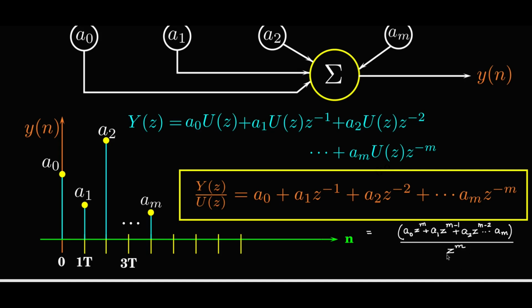However, all the poles have to be at z equal to 0. So therefore, in an FIR filter, there is flexibility only in the design of zeros. Whereas in the IIR filter, there is flexibility in the design of the zeros and also the design of the poles. This is the key important takeaway and also the distinction between the FIR and the IIR filters.